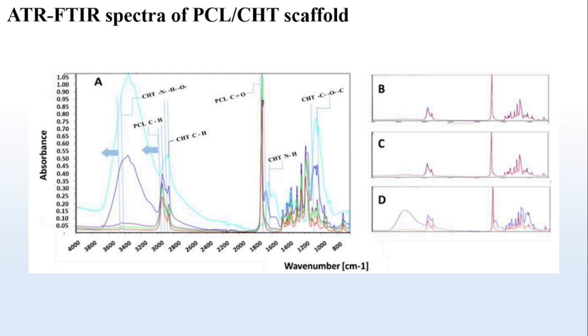However, in the PCL chitosan with ratio 70-30, higher chitosan characteristic peaks on the bottom surface suggest possible phase separation through the membrane thickness. Overall, while no phase separation occurs due to the interaction between PCL and chitosan, separation could occur in the material with the ratio 70-30 due to their distinct chemical properties.